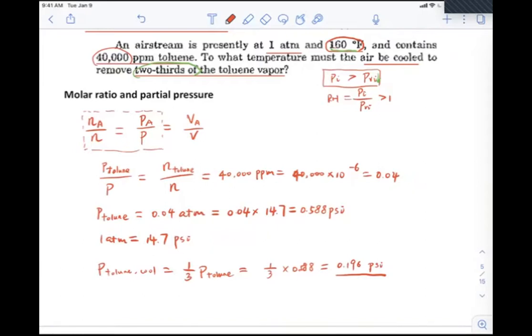If you think about what's happening in the flue gas, when we emit the flue gas from a coal-fired power plant or any industry, typically the flue gas temperature when it first enters the duct is very high. As it flows through the duct, the temperature is going to automatically decrease because of heat exchange with the ambient. So you don't have to create some refrigeration condition to cool down the flue gas. You can just leave the duct like that, and the temperature is going to automatically decrease. If the temperature decreases, the VOC condense, and you can get rid of those VOC.